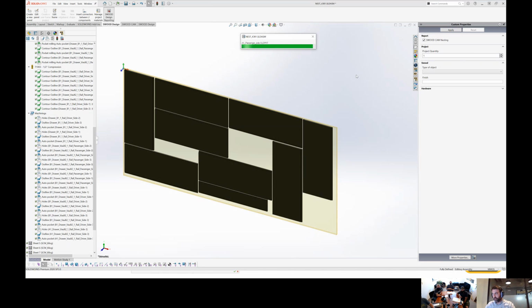To cut parts individually or do a bridge type nesting where basically when you do the cutout, you don't stop that bit until everything's cut out. You connect them all. Not sure to understand. So when we run parts, you can cut out one piece at a time and then lift the bit, or you can have all cuts connected. That way parts don't move until the very end, basically.